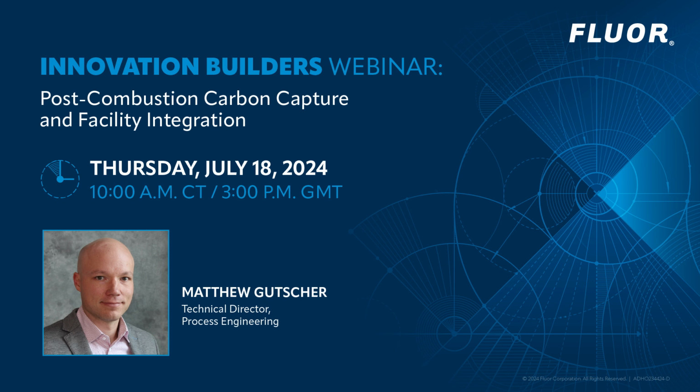Post-combustion carbon capture presents technical challenges including low CO2 partial pressure, the presence of oxygen and other flue gas contaminants, low flue gas pressures, and site allocation constraints affecting the carbon capture plant layout. The design must also account for the significant heating, cooling, and power utility requirements, all of which directly affect project capital and operating costs.